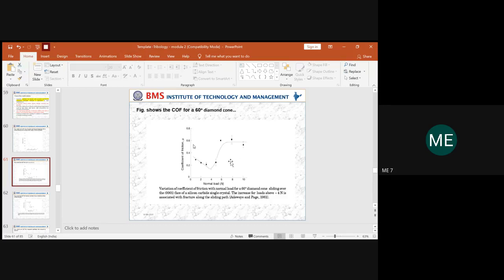Or else sometimes you measure one time, it shows some reading, you try again after some time, and instead of 0.3 it shows 0.6, then there is no consistency at all in what you are measuring. Every measuring instrument should be calibrated well, it should be reliable, and the reading it gives should be consistent. To check that consistency, you should always do the experiment 3 times for one particular reading.